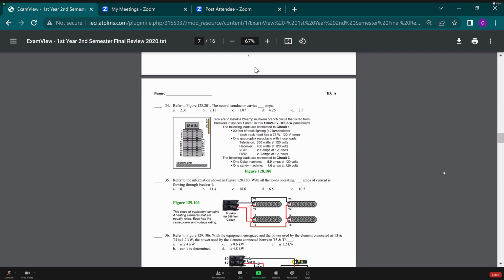If we're looking for total amps, I know that our normal branch circuit wiring is parallel. That's because we want to maintain voltage as much as possible. So in all of this, I know that I'm hooked up in parallel because that's what normal branch wiring is. Okay, so for that, I'm rated at 120 all across the board.